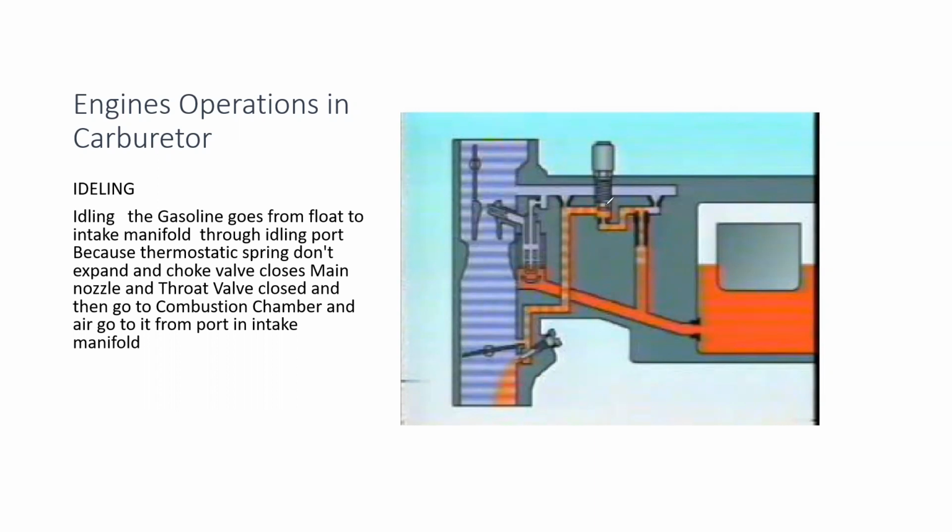So once you turn on the key, 12 volts will be provided to the solenoid valve. It will open this over here for the fuel to flow into this section over here, and be supplied into the system, right? So that's why it's actually there.